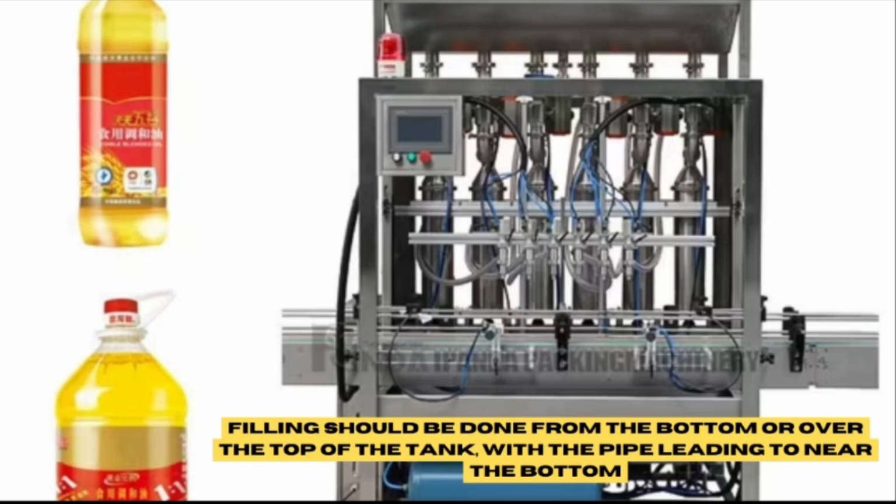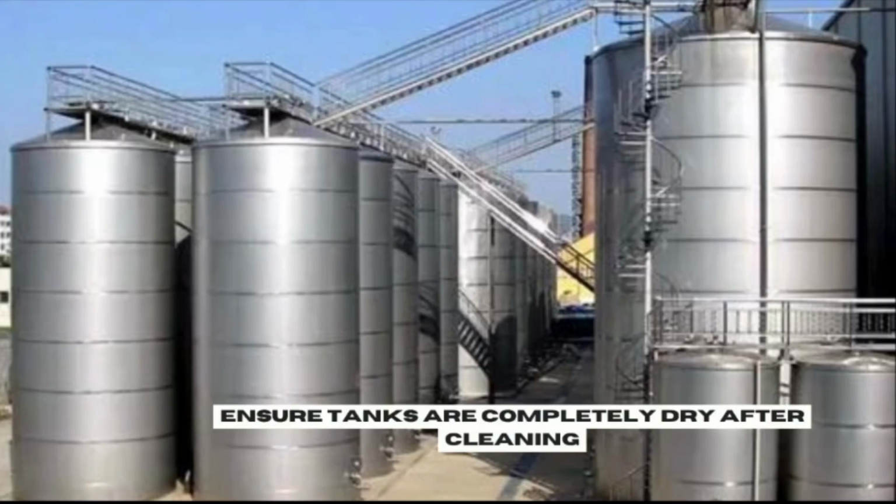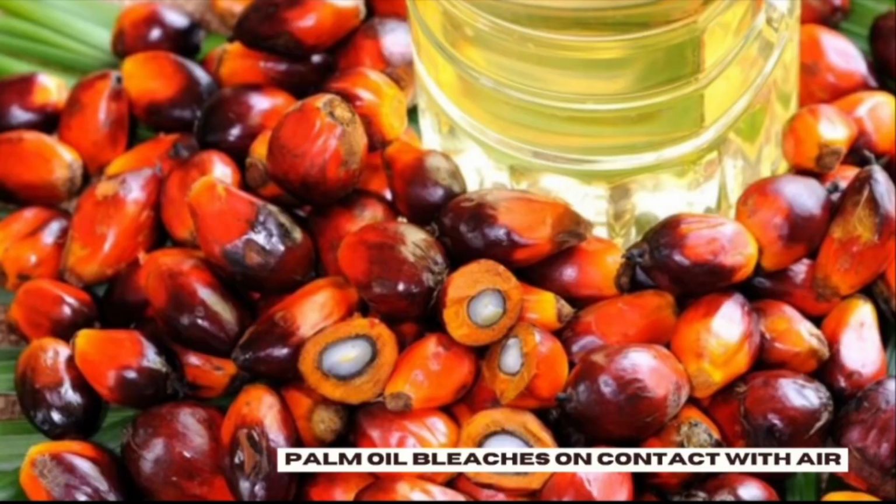Filling should be done from the bottom or over the top of the tank with the pipe leading to near the bottom. Then, do not ventilate the tanks as this will supply oxygen and promote rancidity. Next, ensure tanks are completely dry after cleaning. Lastly, palm oil bleaches on contact with air.